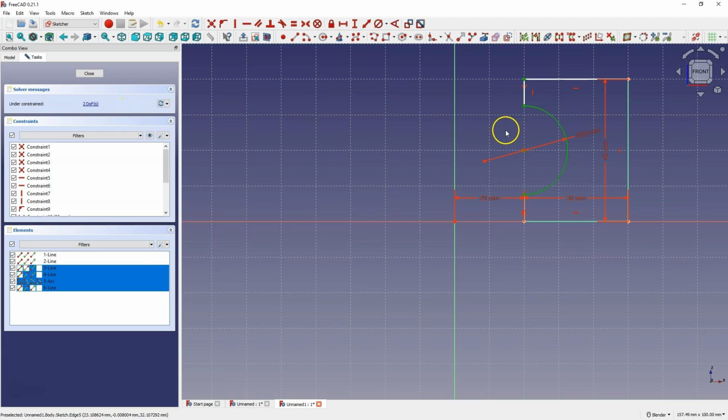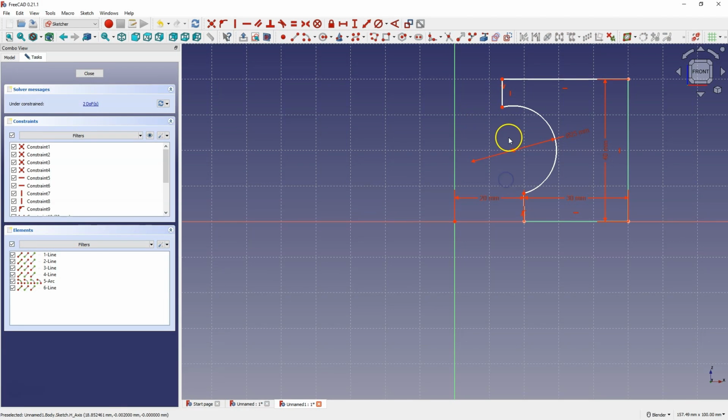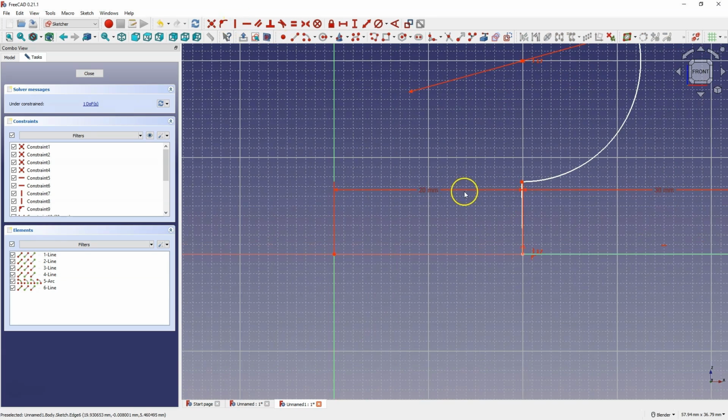And so, to fix this quickly, deselect all the geometries, because as you can see, we already have various geometries selected here. Just left-click somewhere in the workspace, and now select the center of the circle, select this point and select Constrain vertically. And here we already have it constrained, so that the center of the circle is constrained to this point and these points already lie vertically. We can no longer change the position of this point.